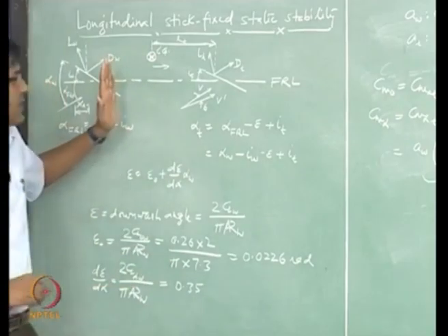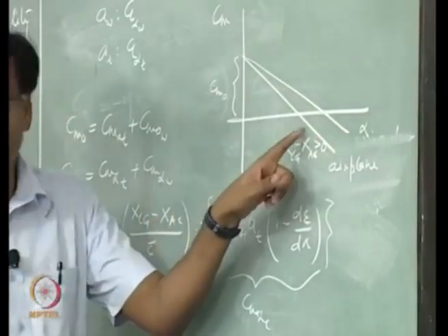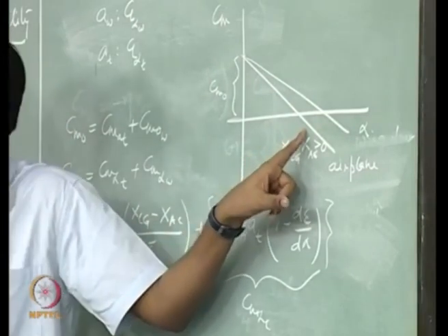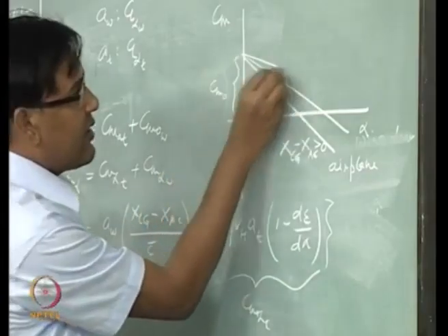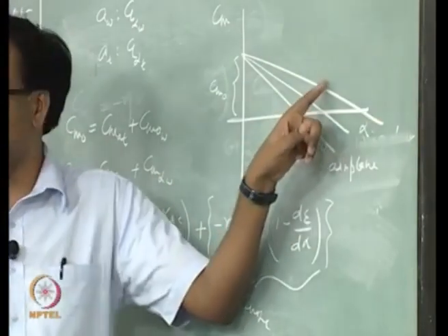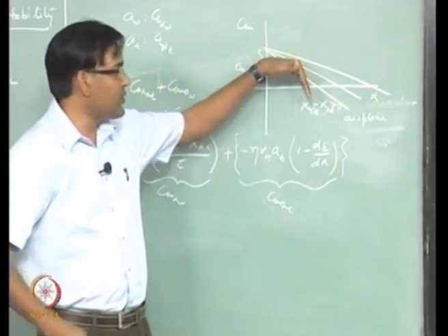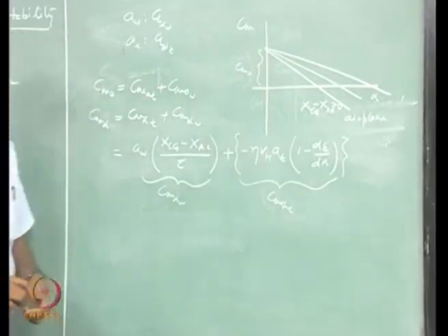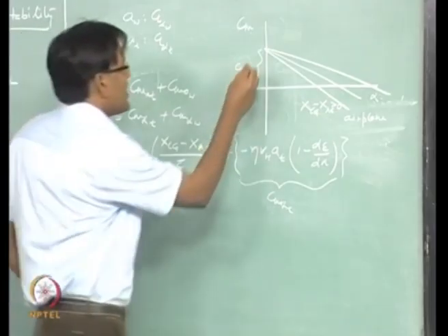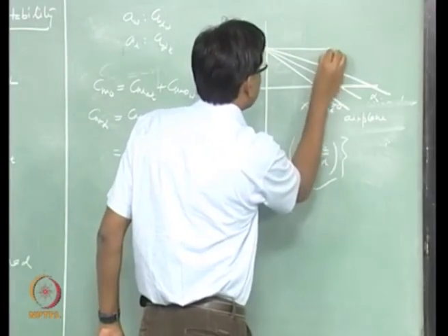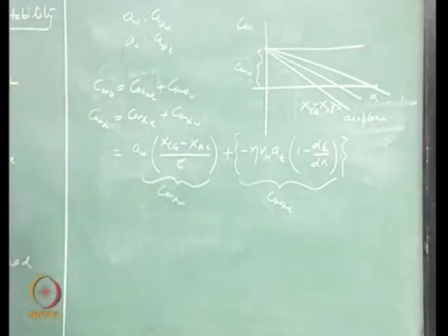So this curve will start now changing the slope. So this is more stable, right, everybody agrees with this. This is more stable than this, right, and this will be more stable than this, right. So you are changing CG and now you see that the slope of this curve is changing, right. So there will be one point at which this curve will look like this, right, it will become flat.